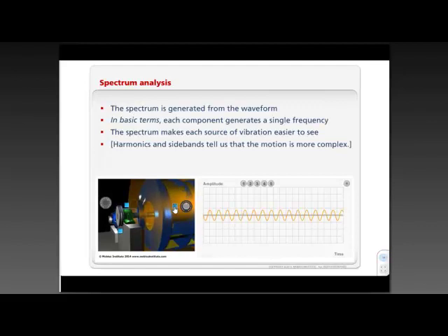And likewise, as we just went through with the fan, this one has more blades on it, but we can see that if the fan was all uniform, the blades were all smooth and the airflow was good, we might not see much of this vibration. We probably will see some, but if there was more of a problem, then we get higher amplitude. But as you've seen, when we combine all 3 sources of vibration, which is this red signal here, that is what we get from the vibration sensor. So when we put the accelerometer on the machine and we look at just the raw time waveform, just the raw motion of the machine, this is what we're actually seeing.